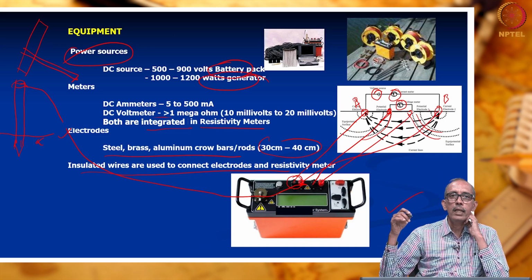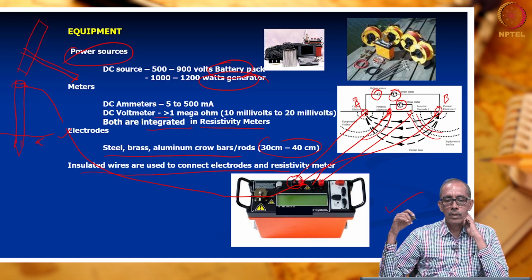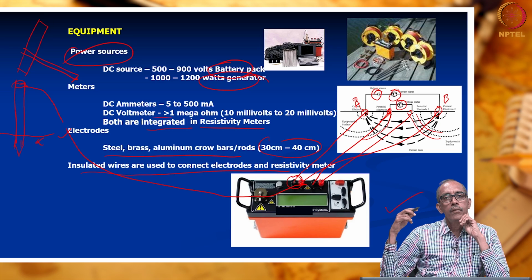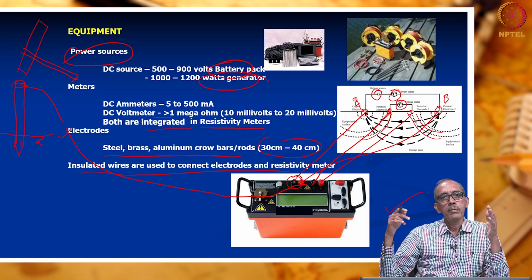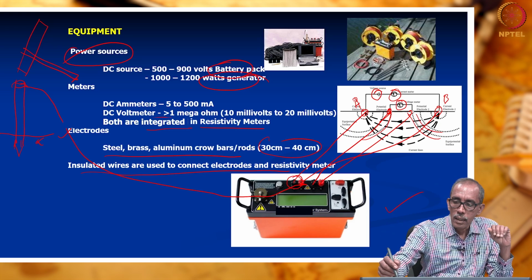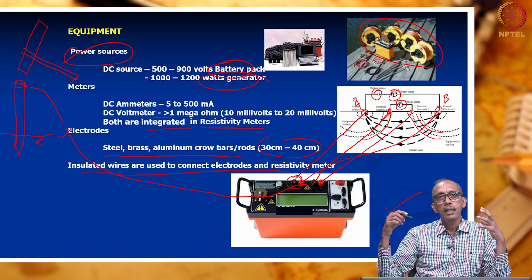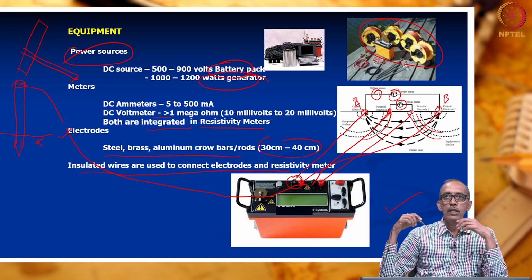So this is how we connect all the 4 electrodes to the resistivity meter, for which we need sets of cables. We may keep the electrodes at different distances, so we need cables in the form of spools for easily managing the wires in the field during the field work. The wires are wound on these spools.